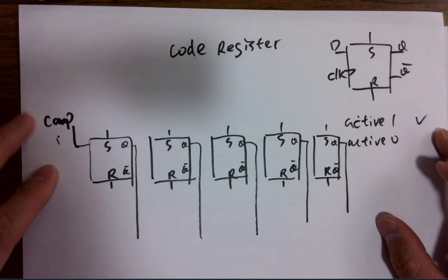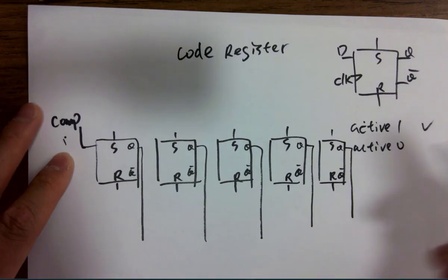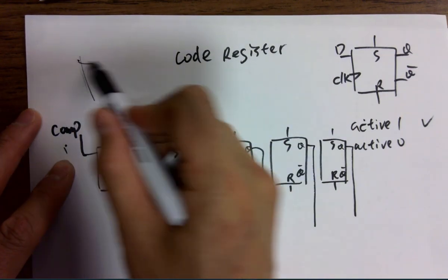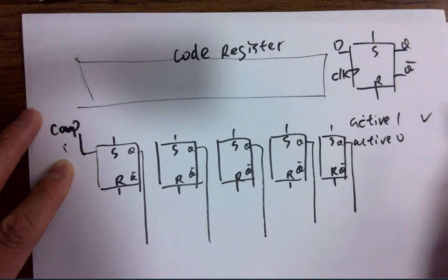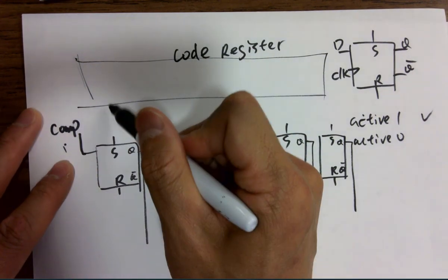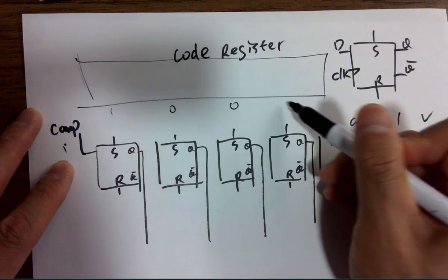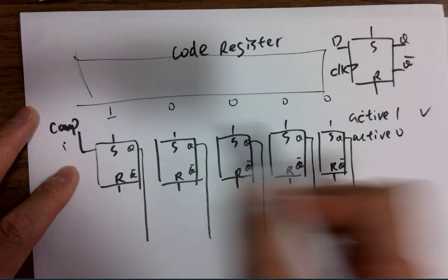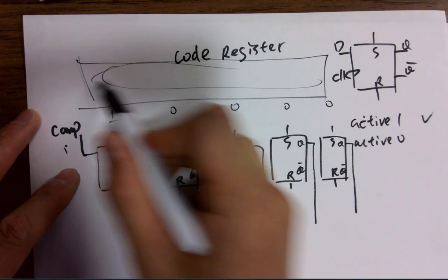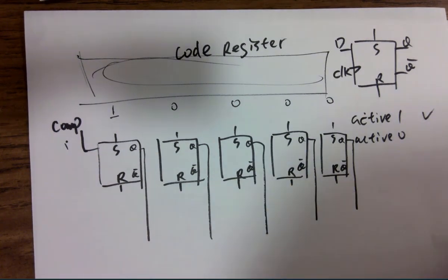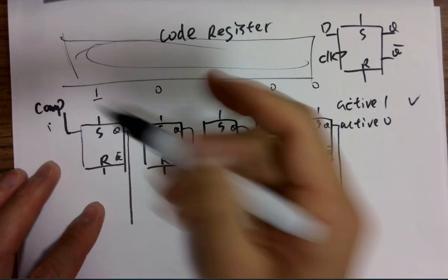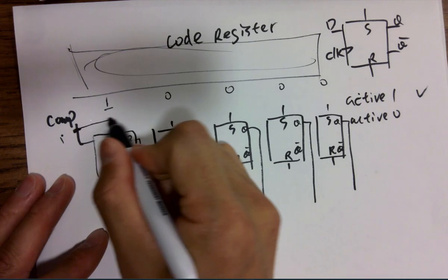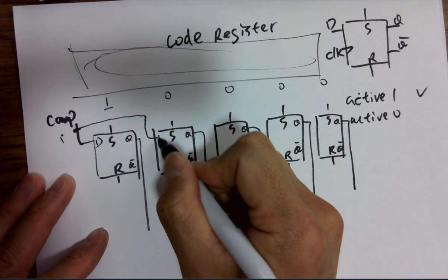So for this, it looks like this. And we assume that there's another block on the top. We'll shift ones from left to right. It's giving a 1 at O0 at the very beginning, and it's able to shift that 1 to the right sequentially. We don't know what the circuit looks like; I'm going to introduce that circuit later. But now let's assume this is going to happen. And these comparator outputs are being fed into all the D digital inputs.